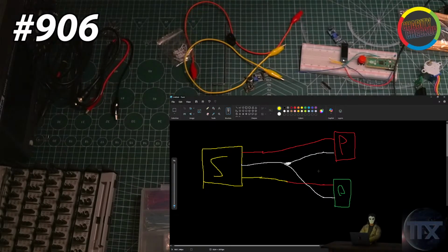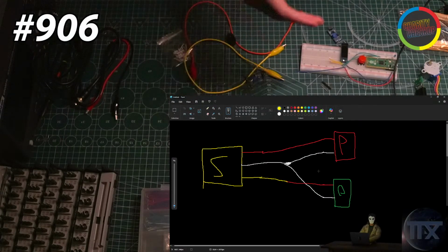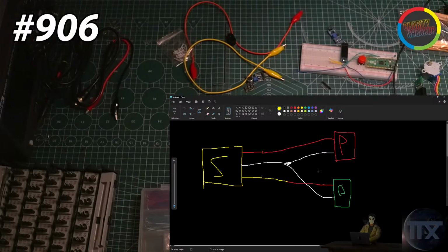Or even like a classical example, like with the ESP, there was this pin on the ESP, wasn't there, that was interfering with... 18, yeah. Exactly. Off the top of your head, if you're teaching someone how to use an ESP, you probably would mention it. But if somewhere down the line you're working on a project and you get interference on the pin, or even worse, some kind of pin isn't sending data properly, then you would know that it's interference because of that reason, whilst the person who is new to it probably wouldn't.